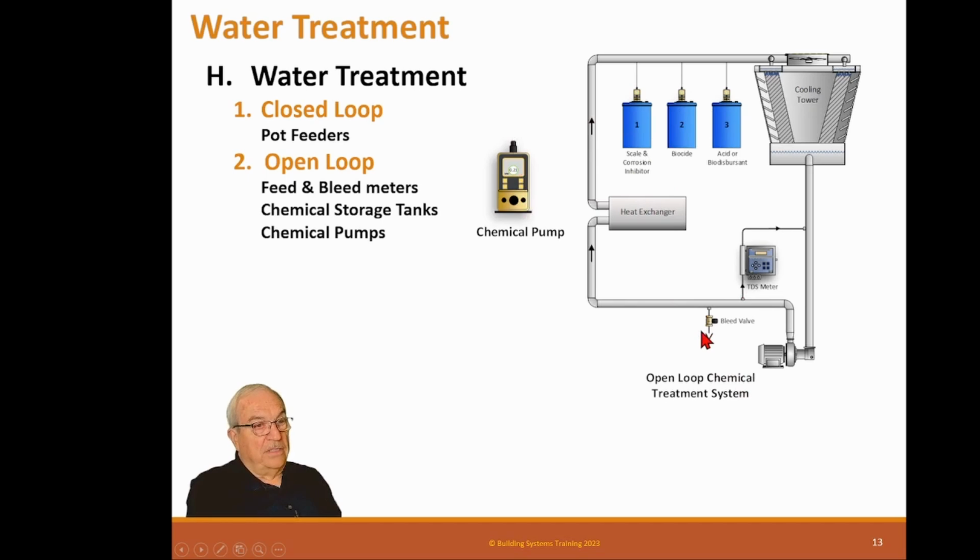So the thinking, which is pretty smart, is when we've got high TDS and we're bleeding, we're feeding water, which needs chemistry. So as long as it's feeding water, we're pumping chemistry in it. And these are all separately adjusted. The chemical treatment contractor basically adjusts all this stuff. And the Achilles heel of this system is if their tanks are empty.